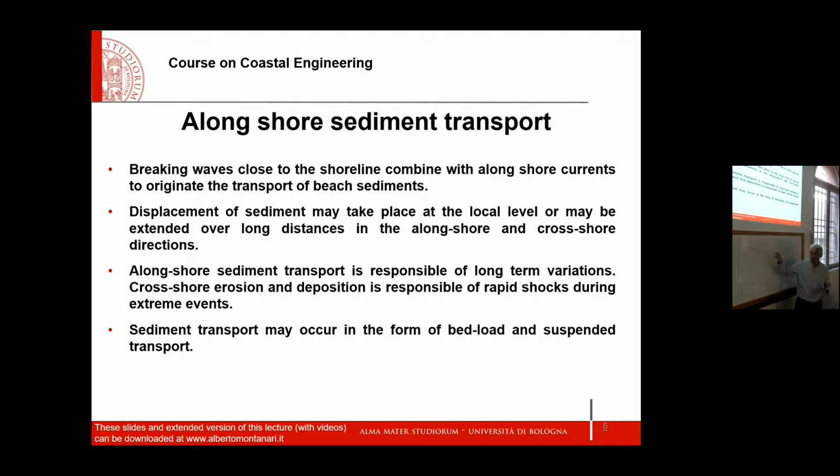And the breakwaters give the feeling that something is unnatural, it's artificial. And because they take the visual, you don't see the skyline if there is the breakwater. So in some cases, we use submerged breakwaters in order to limit the visual impact. Of course, also their efficiency to stop the across-shore sediment transport is reduced for obvious reasons.